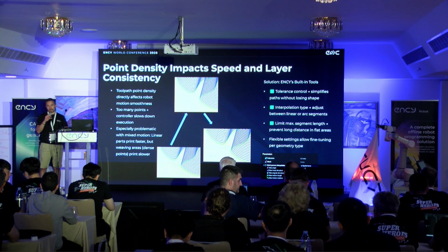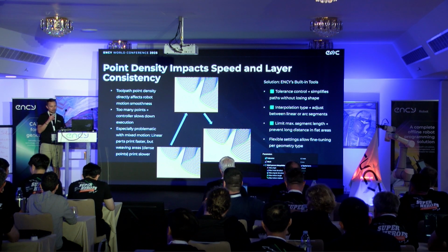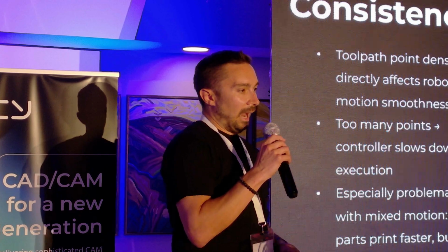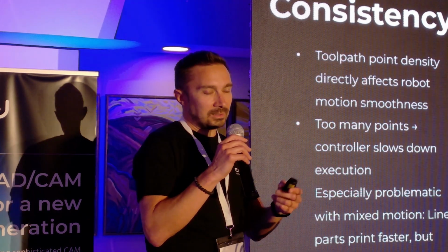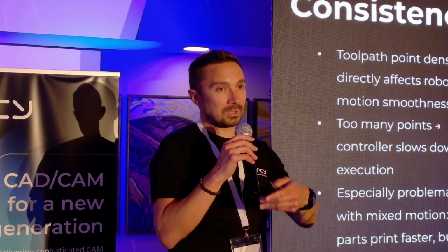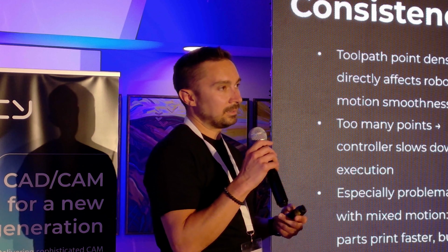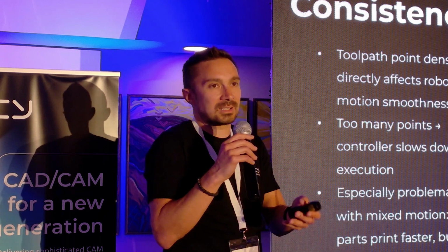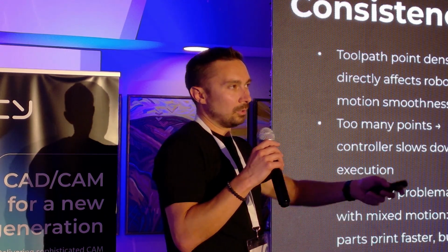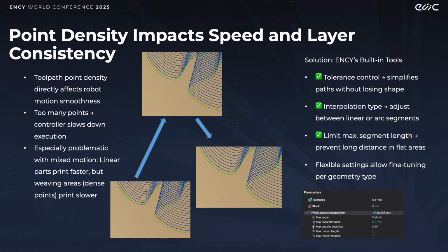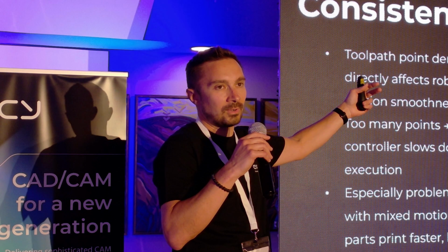Especially worst case when you have 2 points at the same place, and it negatively influences the robot speed, and especially with concrete, we cannot stop the pump. You have seen in the picture of the whole cell, we have the tube 3 or 5 meters long.